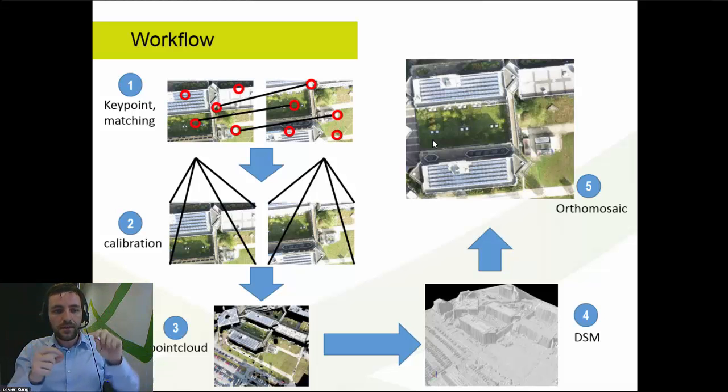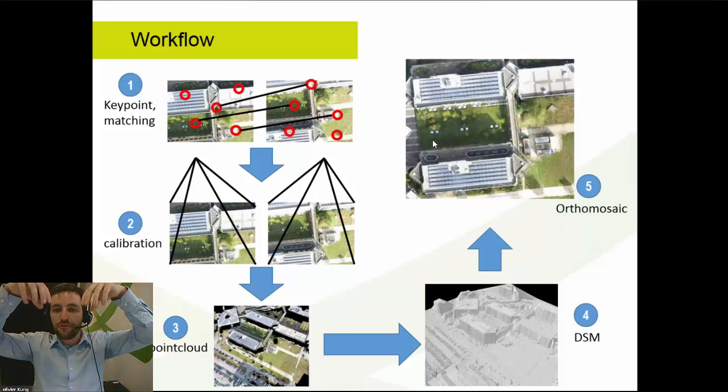When they are analyzed, there will be some key points, some places where the software will look and try to match them across other images and make correspondences. This is what we call key point matching. I just drew here on the example 5 key points, but in general you'll have tens of thousands of them in each image.